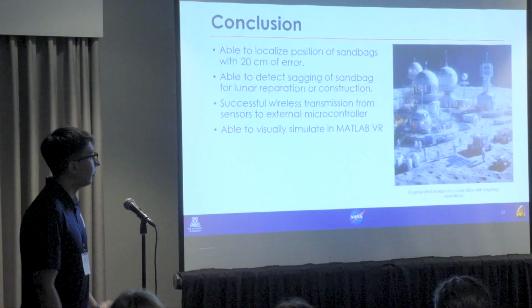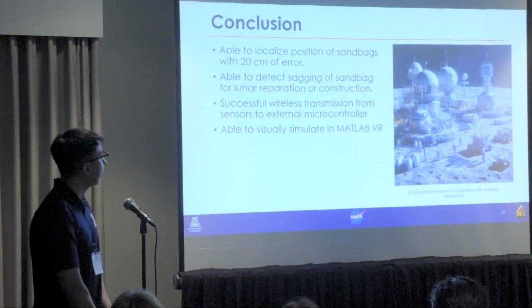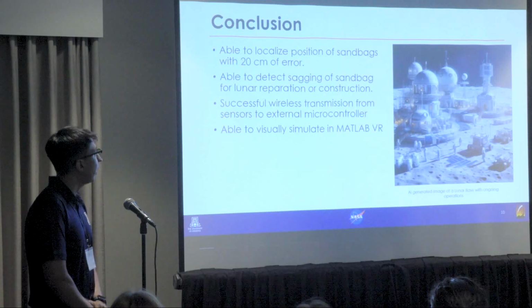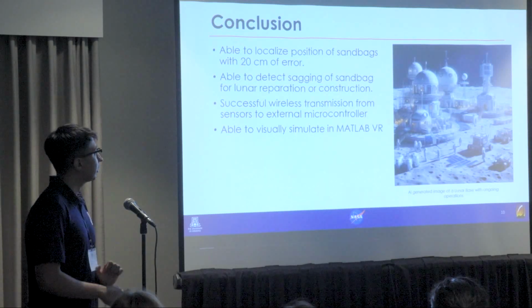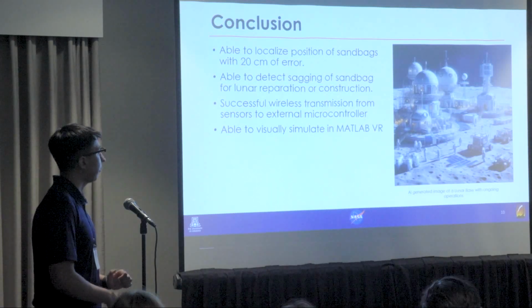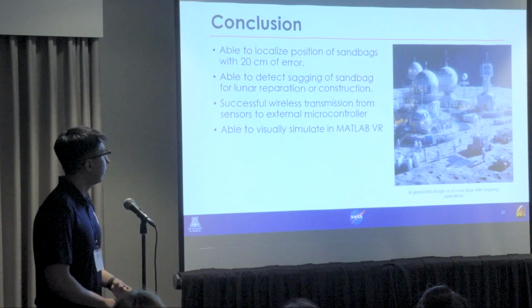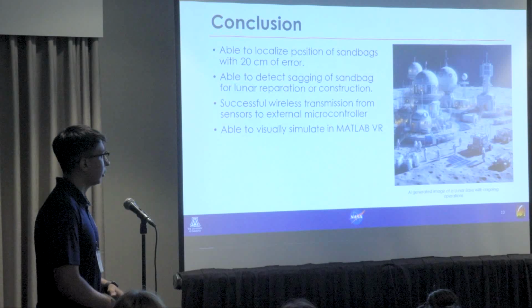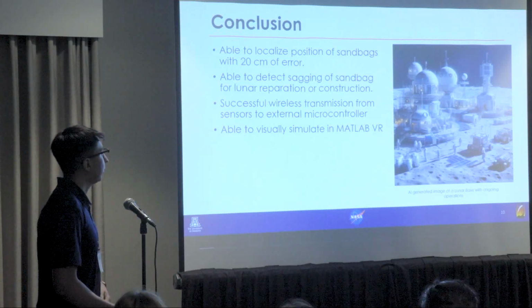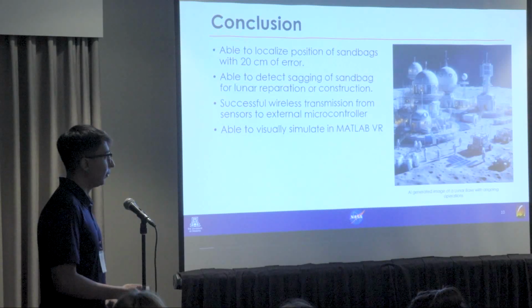So in conclusion, we were able to localize positions of the sandbags within 20 centimeters of error. We were able to detect sagging of the sandbag for lunar reparations or construction. We were able to successfully wirelessly transmit from sensors to an external microcontroller that was our gateway. And we were able to visually simulate this in MATLAB VR.